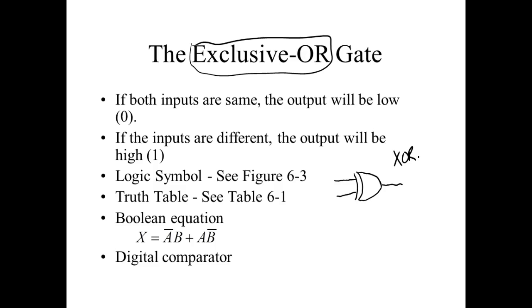Now, these guys are looking for whether the two inputs are the same or different. It's going to give us an output. And what we have to do is figure out what indicates they're the same and what indicates they are different. The symbol shows us what we get if they are not equal. So this guy says we'll get a 1 if it is not equal, because I don't have that circle right here, right? Everybody okay?